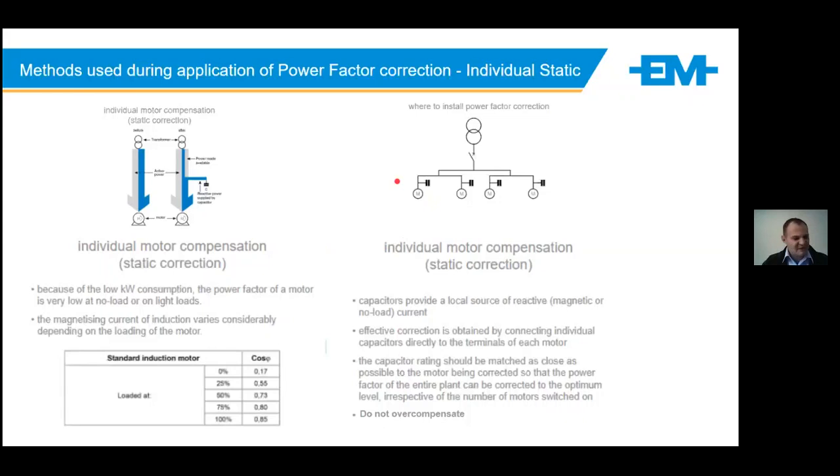We've seen historically that the customer would literally connect that capacitor straight onto the motor. The problem there is, depending on the function of that motor, imagine it's driving a fan, for example. When the voltage supply to the motor is stopped, the fan could continue to make that motor turn.